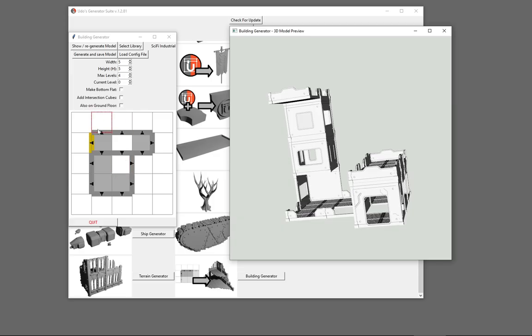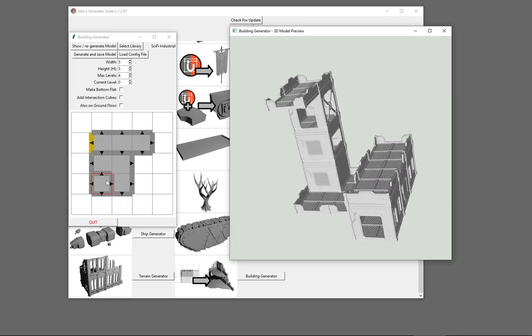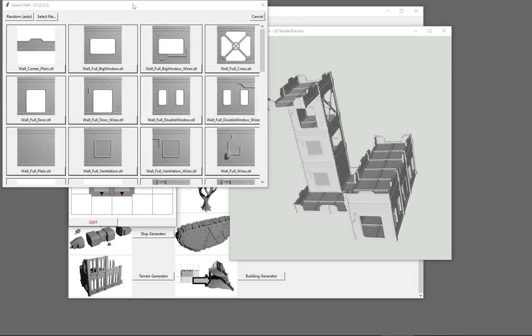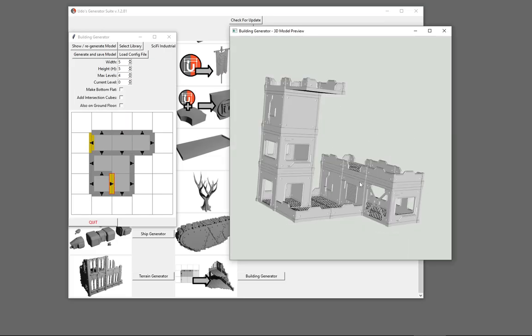Well, yeah, that's basically how it's used. You can build walls, you can build floors. Of course, if you do something like here where we don't have walls, and then on the first floor we have walls, the tool won't check it. That's your responsibility to actually build proper buildings. So if you want to support that, we can just go to the lowest floor and add walls like that. And then of course we probably need a door. So again, just right click here. Let's take this door and do it once again.